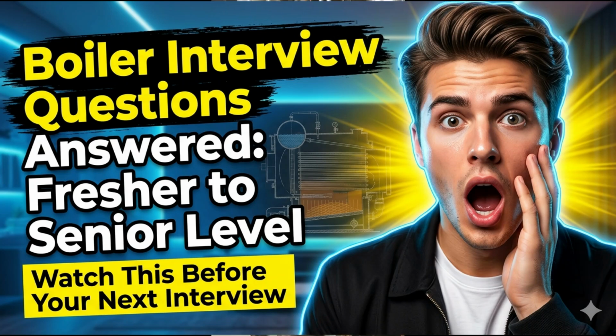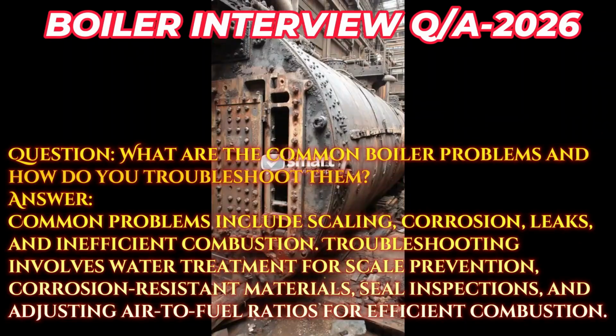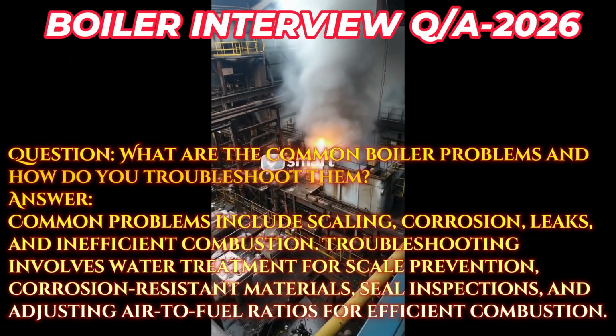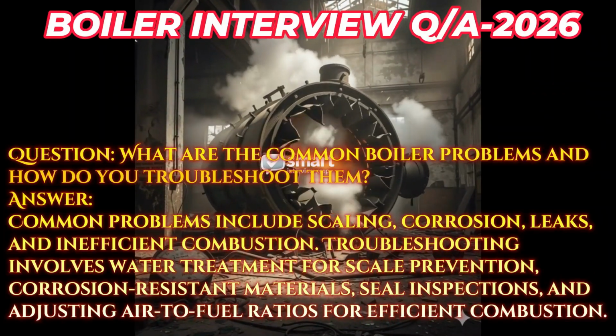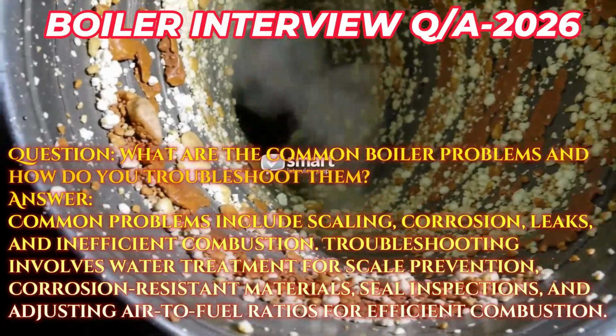Question. What are the common boiler problems and how do you troubleshoot them? Answer. Common problems include scaling, corrosion, leaks, and inefficient combustion. Troubleshooting involves water treatment for scale prevention, corrosion-resistant materials, seal inspections, and adjusting air-to-fuel ratios for efficient combustion.